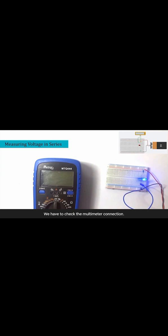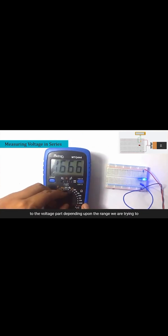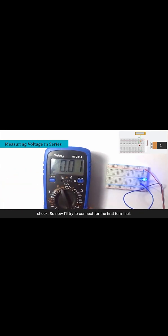First, we have to check the multimeter connection. The positive should be at the V and the negative should be at the common. And now we'll shift our knob to the voltage part depending upon the range we are trying to check. So now I'll try to connect for the first terminal. You can easily see I am checking across the resistor. The voltage across the resistor is 4.65. Now let's check voltage across the LED, which is 3.42. So as we can see, the voltage across the terminal is dropping.